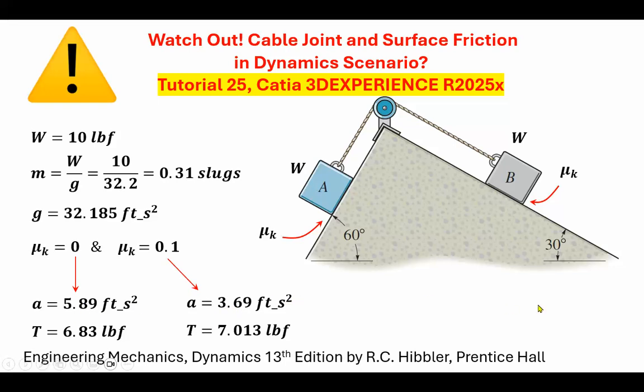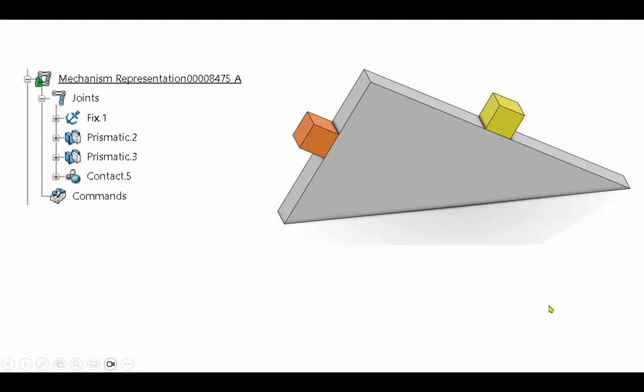Now, here's the way I'm going to do that. I will create two prismatic joints associated with the block on the left and block on the right. The prismatic joints are going with the ramp, one between the orange block and the ramp, the other one between the yellow block and the ramp.